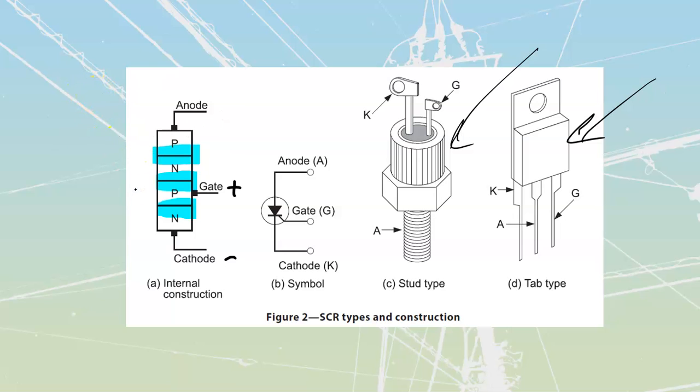Remember how we used that analogy of the fact that you can't blow up one side of a balloon? Well, as soon as you put this one into forward bias, you're at the same time putting more holes into this P type of material, which is going to shrink down this one. And if this one is shrinking down, that in turn is going to cascade over and shrink down this depletion region over here. And what happens is that, end to end, all of a sudden we are going to have current flow that can go through from our cathode, or more negative point, all the way over to our anode.